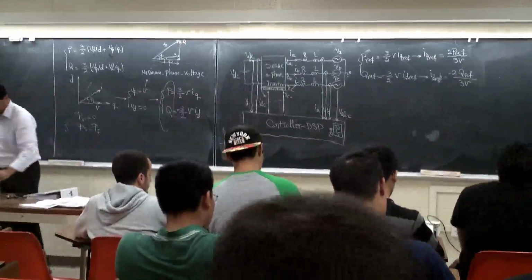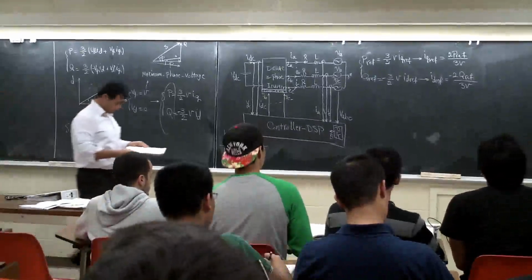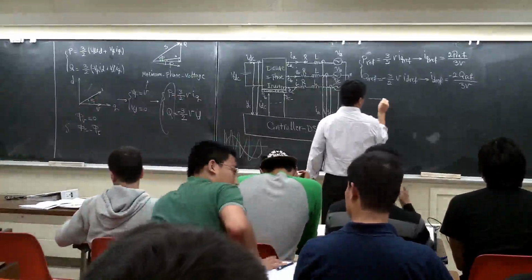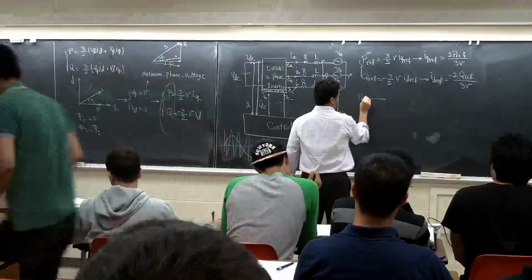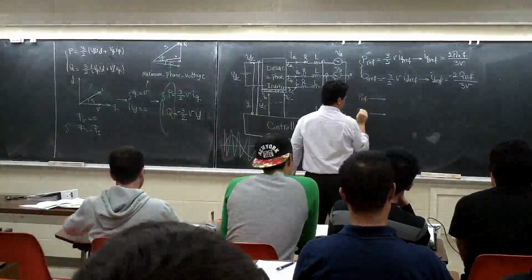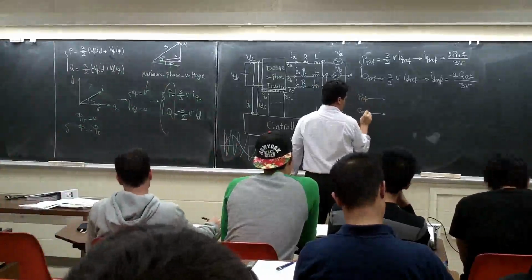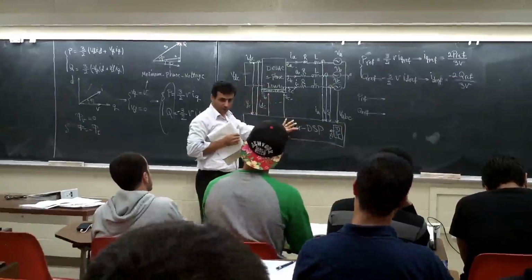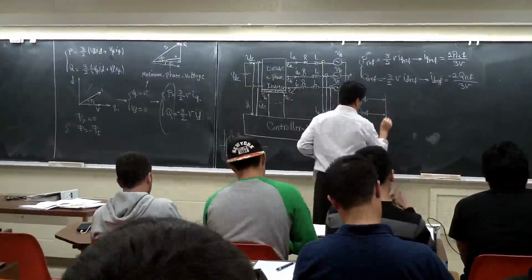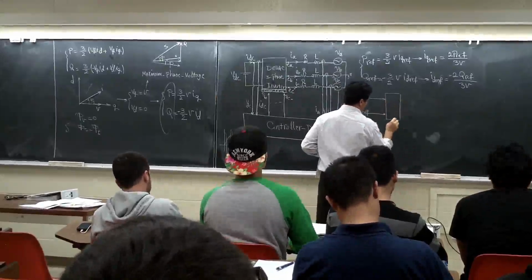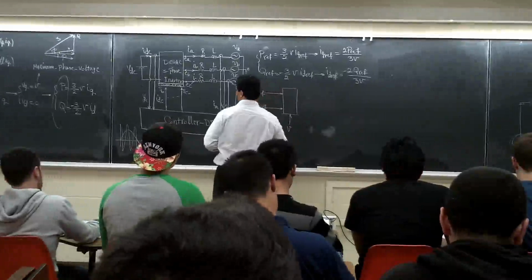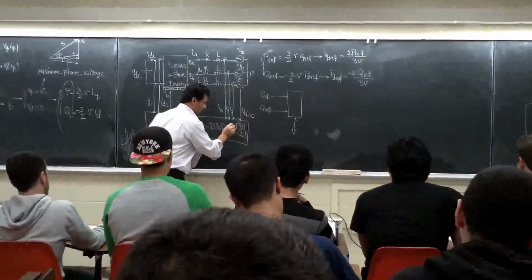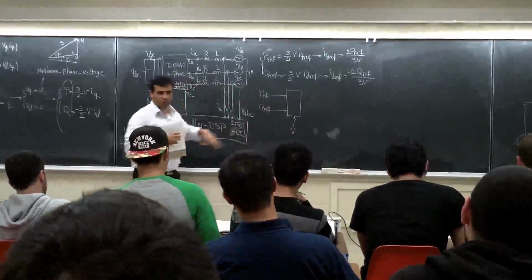So now I have this one. I'm going to put the block diagram together here. I'm going to bring my PREF, my QREF. See, this one is all happening inside this box, right? This is the controller. I have a box here, a math box. It's going to get V as an input. How are we going to calculate V? This PLL is going to give you theta and V both. Theta and V, both are going to come from the PLL.